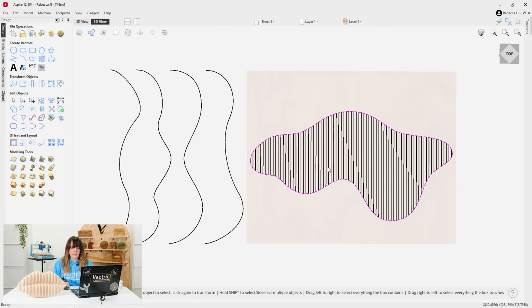Every one of these lines is going to represent the position of our slot. It's also going to represent the back side of each one of our profiles, which will make more sense as we go on. And so the important thing here is that we create the profiles and those slots here, and then we can look at further organising our part by sheets to ensure that we don't have any crossovers, we don't make any mistakes.